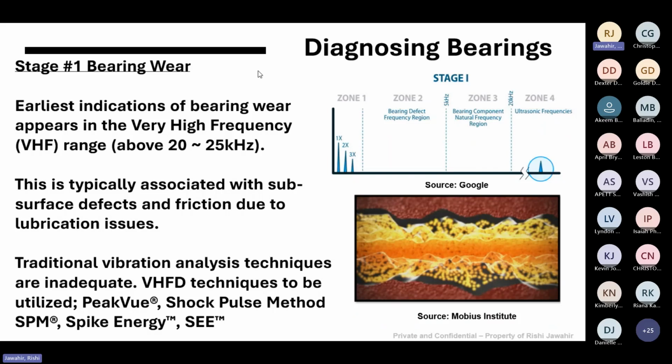You could see in the image below uneven surfaces, at the microscopic level, of the two surfaces, whether between the outer race and the balls or the inner race and the balls. This is because there's no ideal perfect surface out there, and that's why lubrication is important to keep an even film across rotating components.